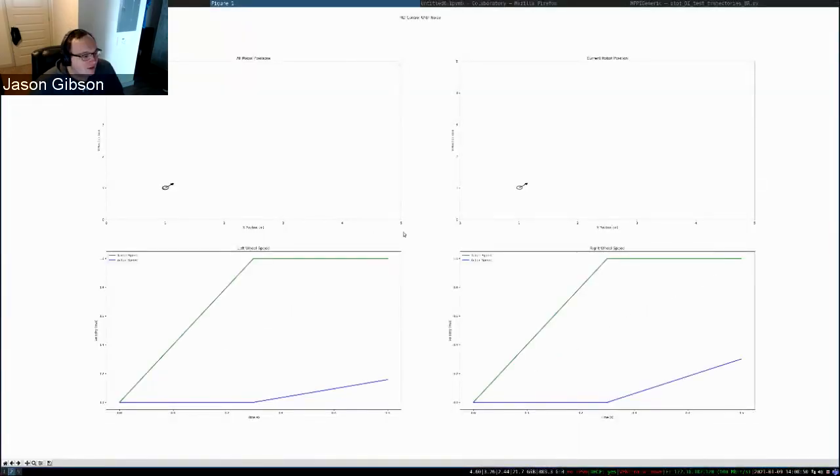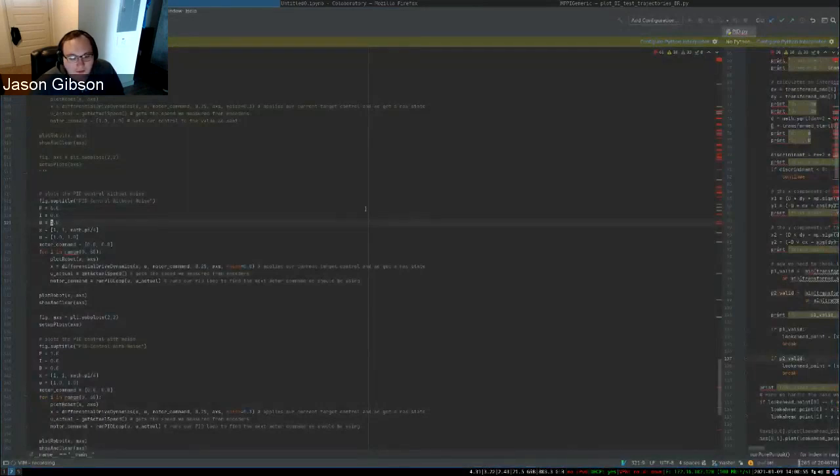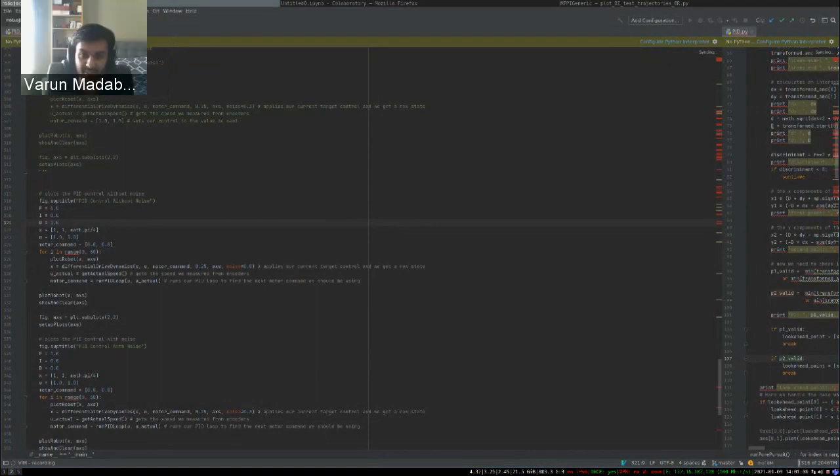So now, sorry to interrupt, Jason. We got a question in a direct message to me: are there programs to automatically tune your PID? So the answer is yes, to a certain extent. In order to tune the PID, you have to understand exactly how the system works. And if you want to do that automatically, it means that a program has to move the robot, see how the robot reacts, and then change the PID loop's gains on itself.